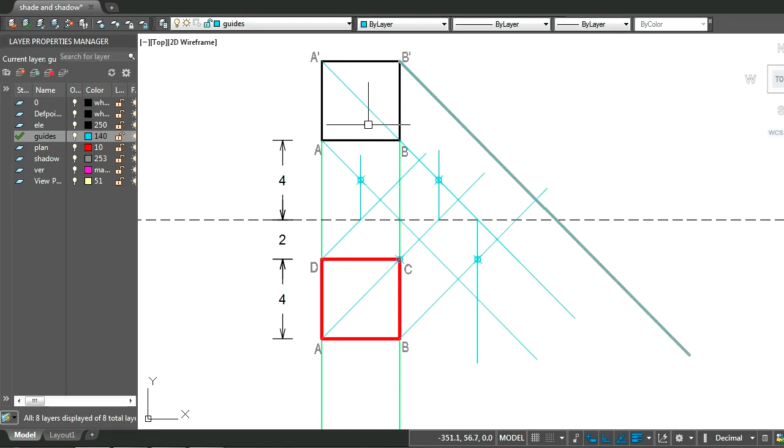Okay, so we have two light rays similarly coming in from the top of the object. So for this, we'll again go back to A and B, since it is the same points that we refer to for the bottom of the cube as well as the top of the cube. Like we took for A and B in a straight line, similarly A and A dash are in a straight line from above or in plan. So now this and this intersect. This point also becomes point A dash.